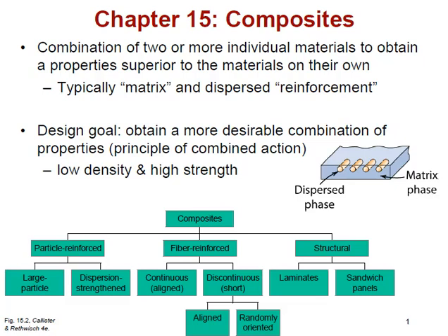Two main parts of a composite: the matrix, which defines the continuous phase, which we saw if you've listened to or read any of the discussions on heat treatment and microstructure and metals, is very important because it tends to define many of the properties. That is less so in composites, but the matrix still plays that important role of connecting the reinforcement together and, most importantly, transferring load. The reinforcement phase is the second part, and it basically does whatever the matrix cannot do, and does it while still being discontinuous in most cases.